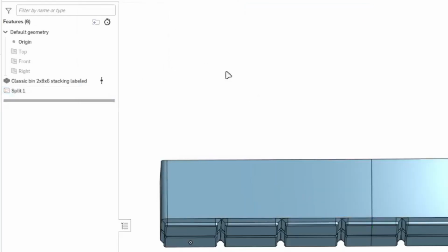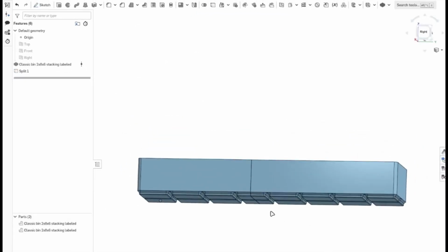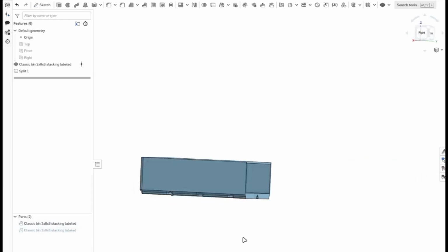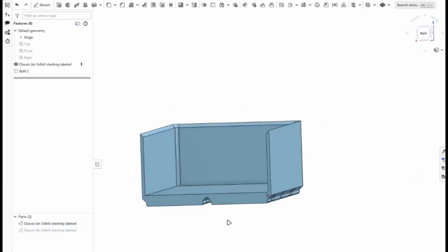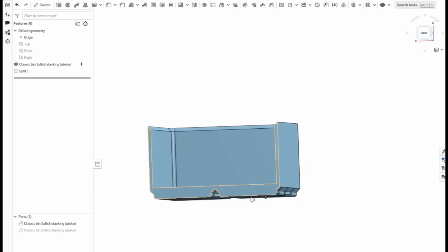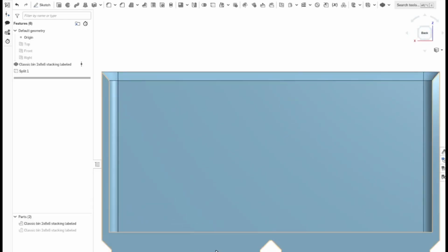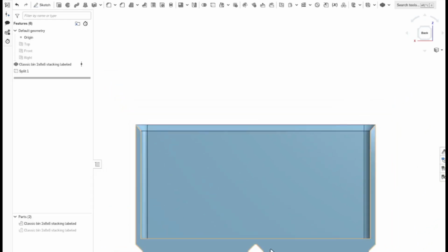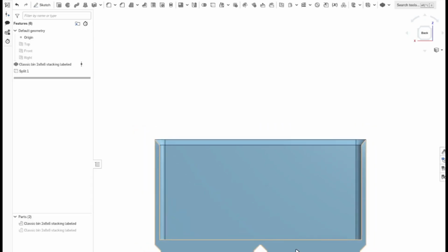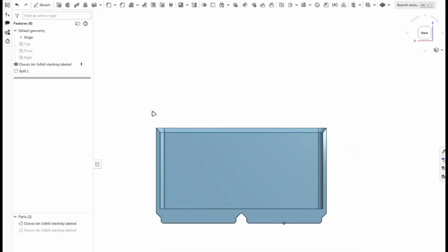Now if you see here, let's hide one. You have a larger contact area, the contact surface is more. Here you can also put some holes, two holes, and then you can have a perfect alignment to join the two boxes, and you can use your leftover filament to join them. So for that we'll have to create some random holes which will be identical on both the sides.